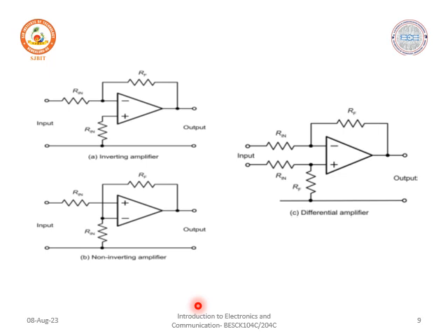So consider these are some of the circuits related to the inverting amplifier, non-inverting amplifier, and the differential amplifier. The first one is the inverting amplifier. In this inverting amplifier, the input is applied with respect to the ground. The non-inverting terminal is connected to ground. So the input is applied through the Rin resistor to the inverting terminal.